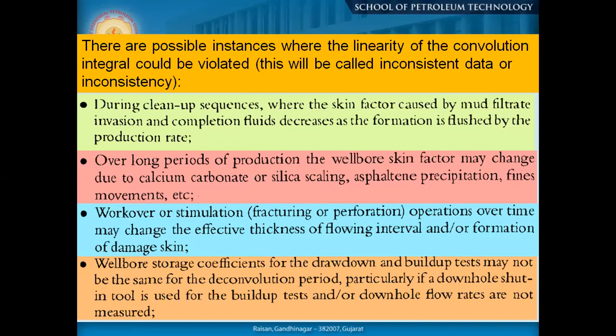Workover is a job we do, and stimulation is the activation or increasing of flow from the wellbore surroundings damage. These operations over time may change the effective thickness of the flowing interval and the formation damage skin. These are some of the activities we do to enhance production for an individual well, and they can change your wellbore surroundings. So if initially you perform a build-up, then you do a workover or stimulation, and then again you do a build-up, and you take the two data together, that will give you different results. So that we will see.